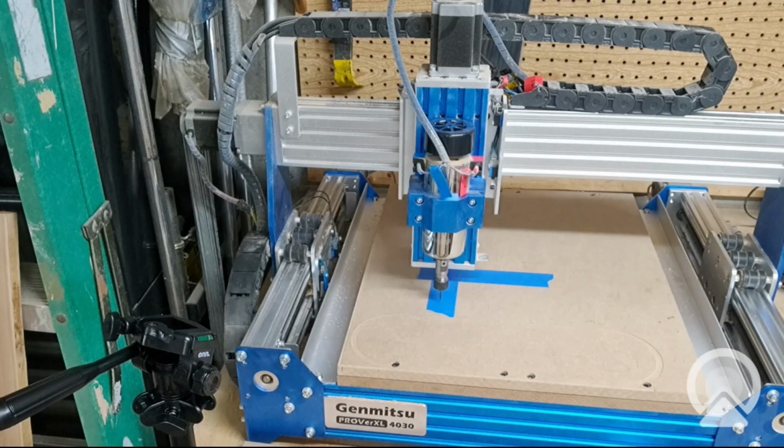Alright, and then come back over, get your tool. You want to use a V-bit, because we don't want to actually drill into our material, we just want to make a mark so we can measure some dimensions. So put a V-bit in there, and then we're going to come back over to the controller. Just make sure your tool's not touching your spoil board yet, or your piece of plywood that you have in there.